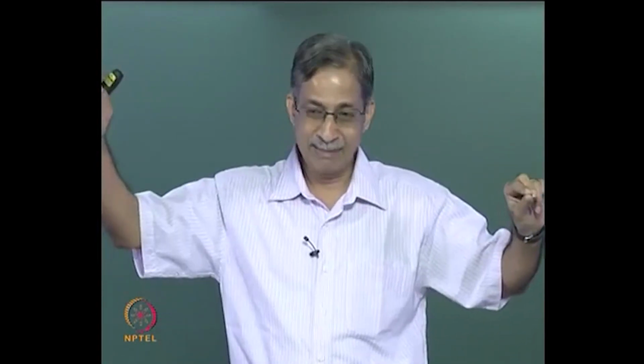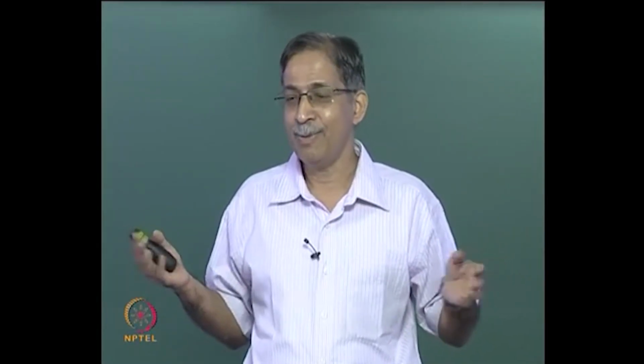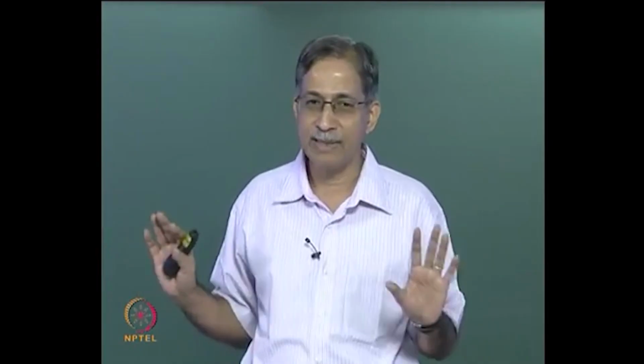So you have differential settlement in that beam, and if the beam is not long, 6EIΔ/L² is the kind of fixed end moment that you will get. That is a huge moment. If you work it out, it is very large, but when you do the frame analysis, you will find you end up with a much smaller moment. But unless you can do that distribution through an analysis, you can't prima facie say whether it is negligible or not. So when you have more members coming into play and more flexibility in the structure, you really don't have to worry too much about indirect loading. It kind of takes care of itself.